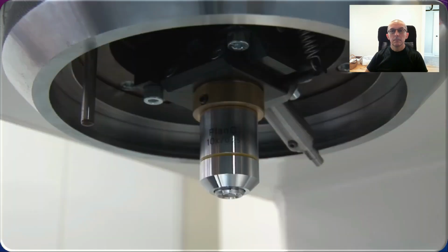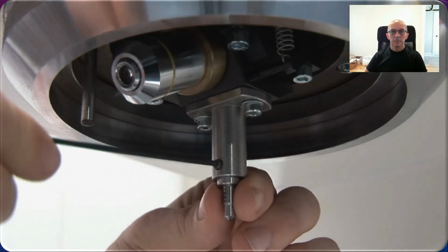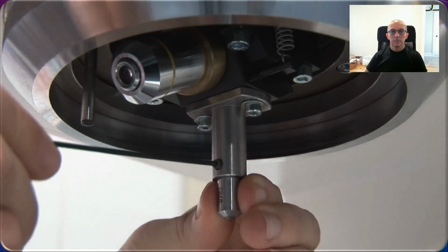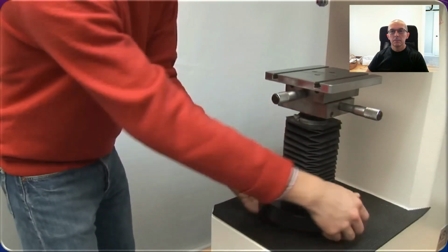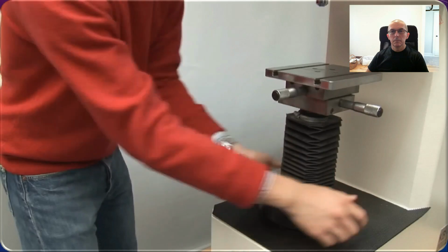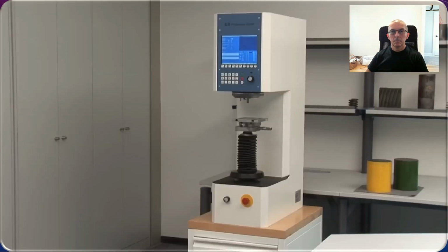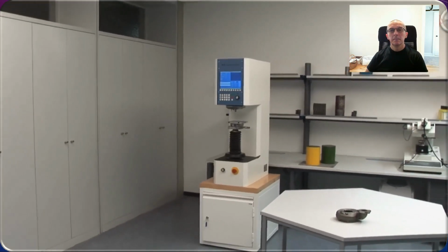Below the control panel, a microscope lens with a digital camera and an indenter are installed. These 2 elements are connected to each other and rotate towards the test piece as required. It is also possible to select and exchange the indenter, so different methods of hardness testing can be conducted on the same testing machine. The support table can be adjusted in height, so the test piece can be positioned at the correct distance to the microscope lens and the indenter. After becoming familiar with the machine, let's start the experiment.